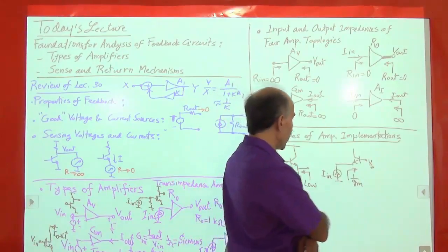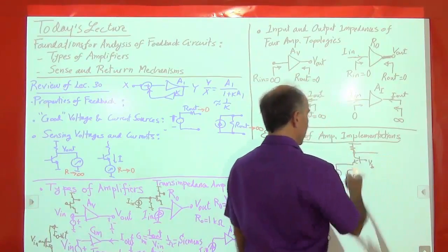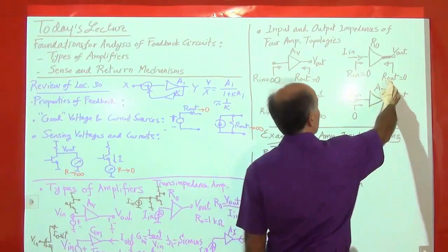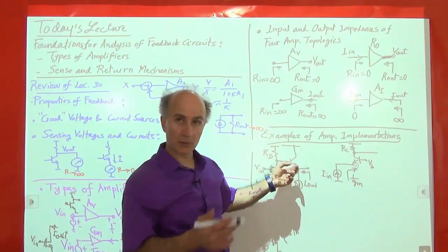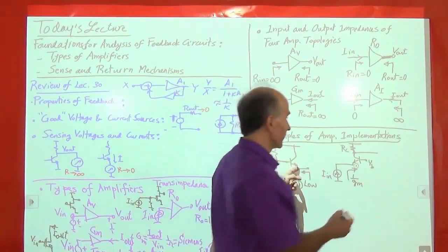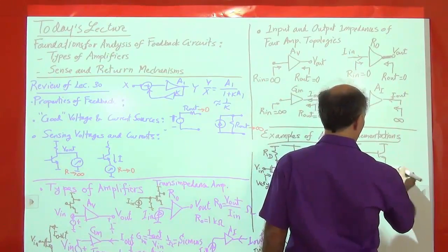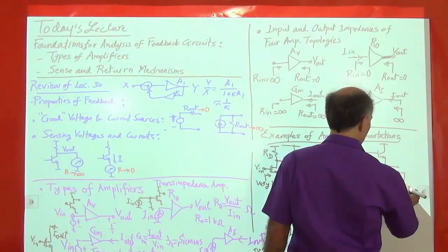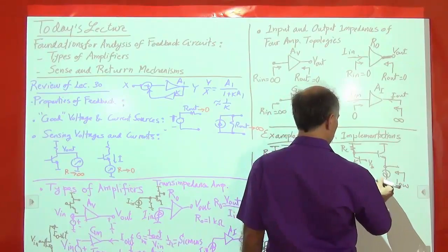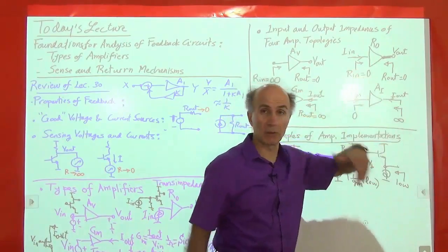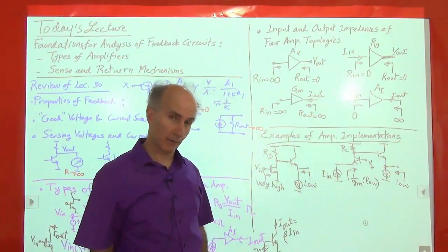That's great, right? Okay, and then we have a resistor here in the common base stage. But again, this resistor is not that small. I am looking for a low output resistance. So just like here, I am going to follow it by some sort of emitter follower or source follower. So here's an example of an emitter follower or source follower. So this has a low input impedance, and this is also low input impedance. So we are coming close to that ideal model. This is a transimpedance amplifier.